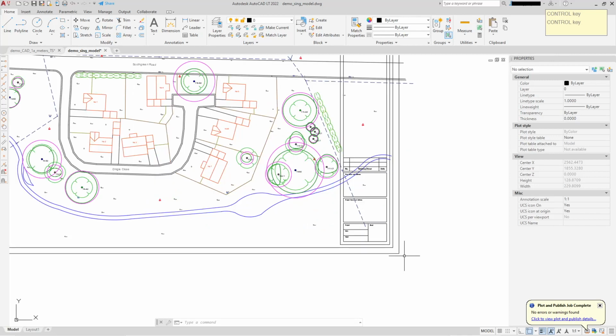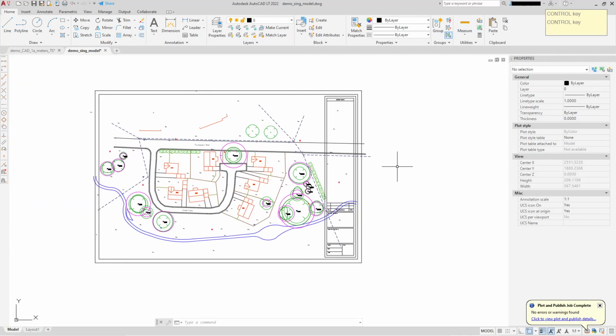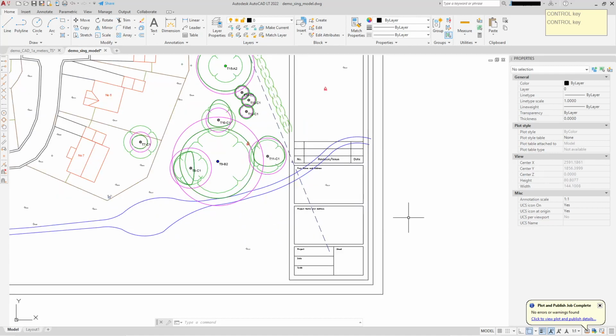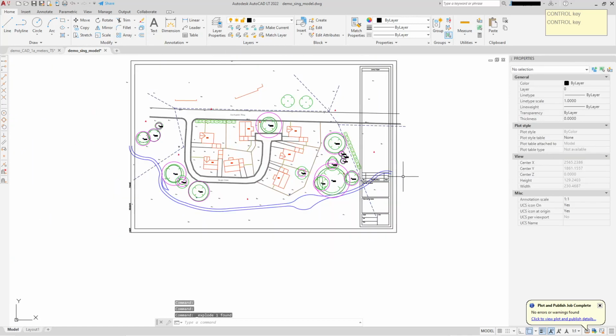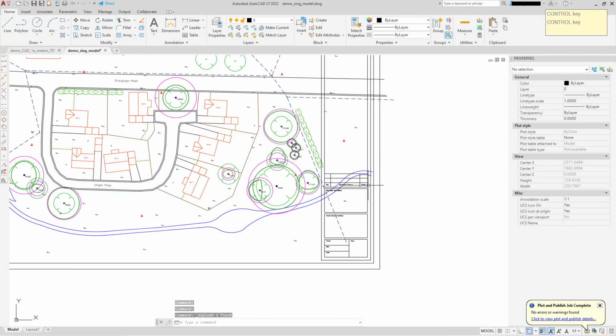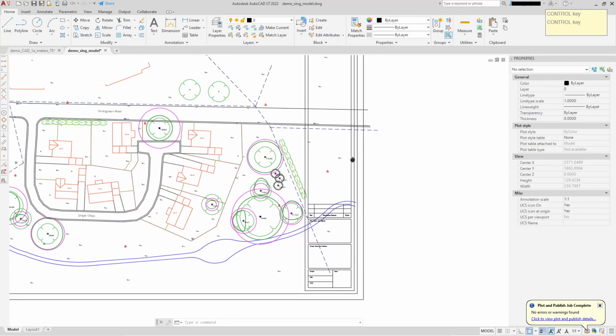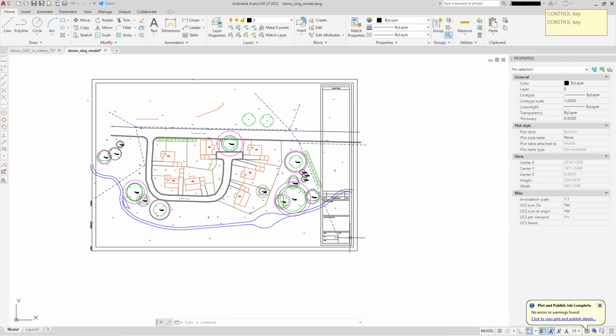And as you can see, it's got its problems. They have a little border, and the drawing's bleeding through. You can see the topo through the border there, these lines, and the key and the logo area. I'm sorry that it keeps flashing. I'll just explode that, stop it flashing. The key and the logo area, you've got the drawing showing through, which means you have to mask this area off, put a wipeout under there or something to hide all these bits of the drawing.